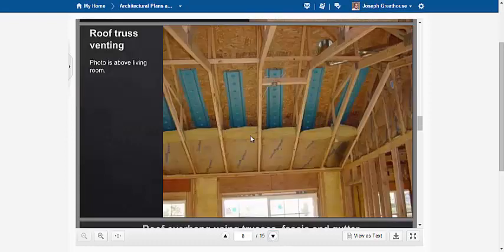The next picture here shows some of the detail of that ventilated roof that we looked at just a minute ago. These are called ventilation or attic chutes. The theory behind that is that we staple these to the underside of the roof, of the OSB, and they go continuously all the way down to the overhang outside. And as we pack insulation into that cavity, we're supposed to be letting the cooler air bypass the insulation, stay inside these chutes, and then ultimately cool off the attic above. Again, this is kind of ridiculous.